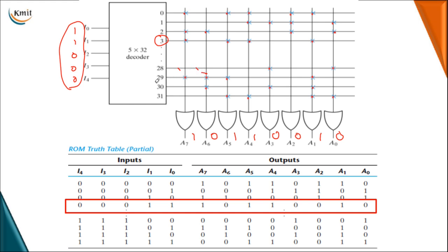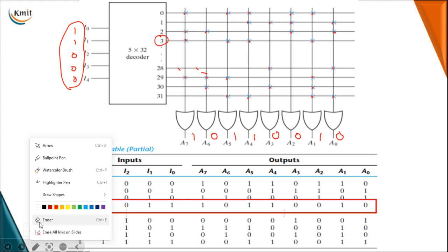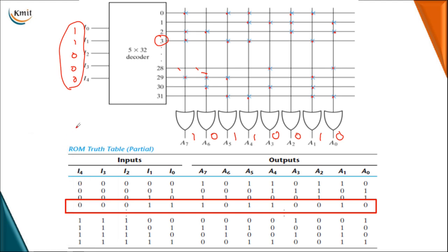by blowing your fuses. So we can store a logical 0 on each word. Actually, users cannot do this; only the designers in the industry can blow the fuses and give you different patterns, which gives you the programming. Once you program that, it will be fixed, so even when your power is switched off, the data obtained from your ROM will not be changed.